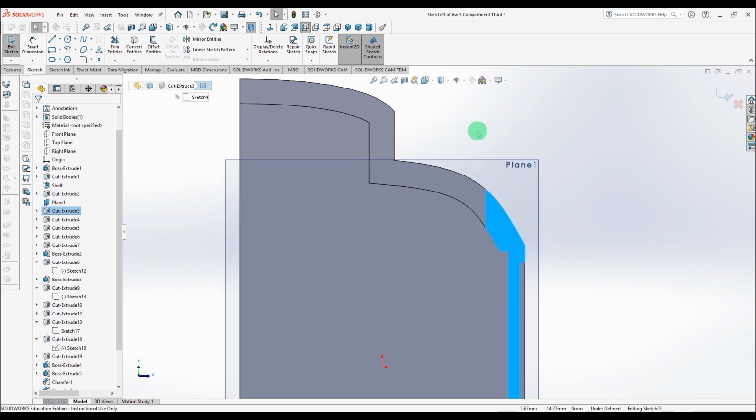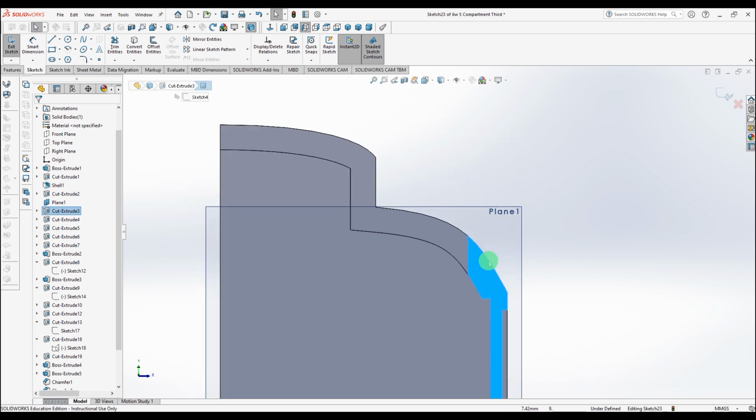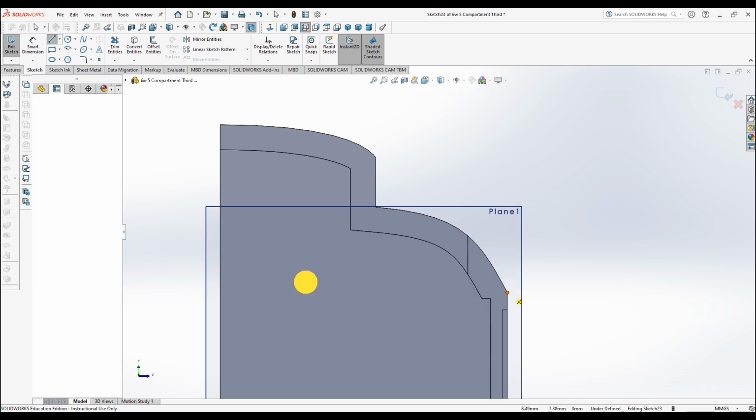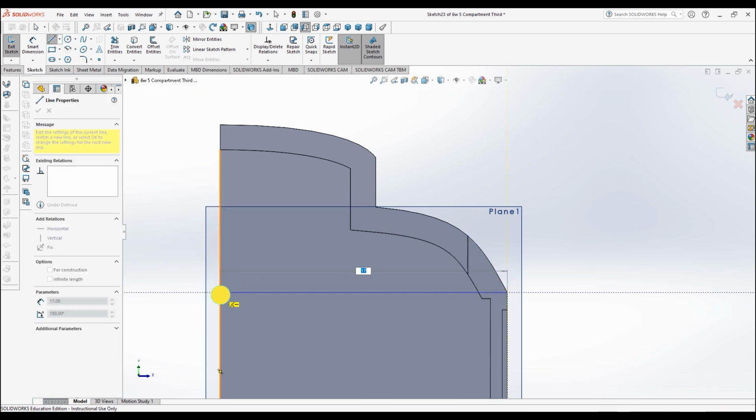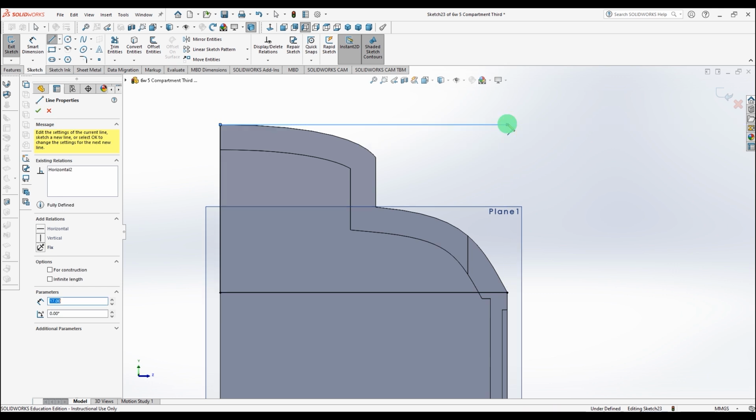Now I don't like this lip that's running around the inside of the end wall and along the roof line, so I'm creating a sketch here, a simple rectangle, which is going to cover those parts that I don't like. And you'll see this when we pop this into 3D.